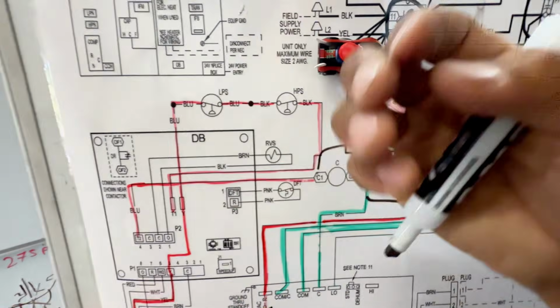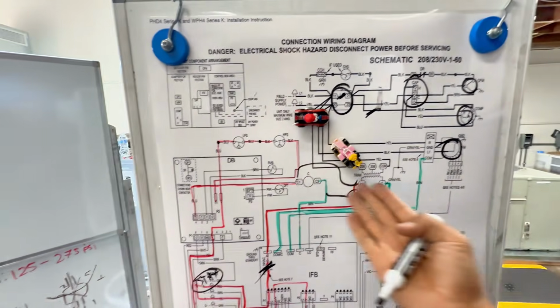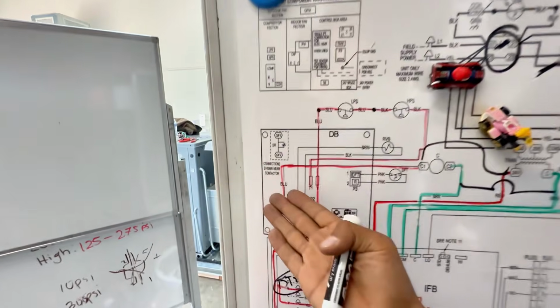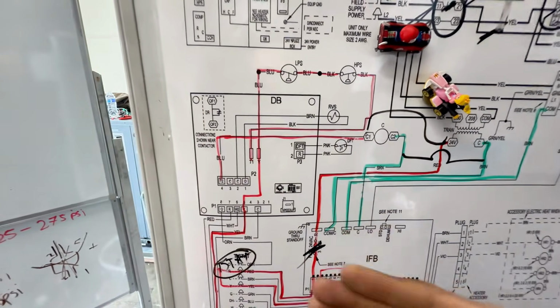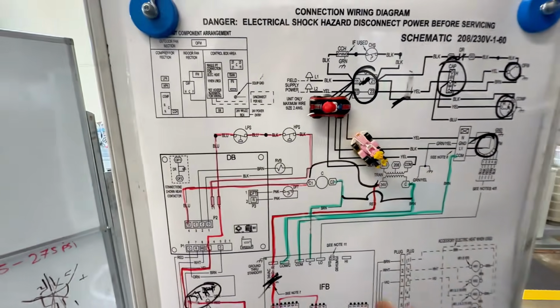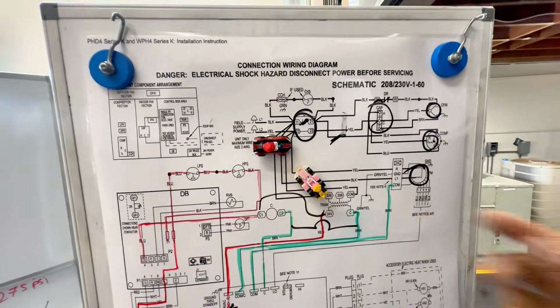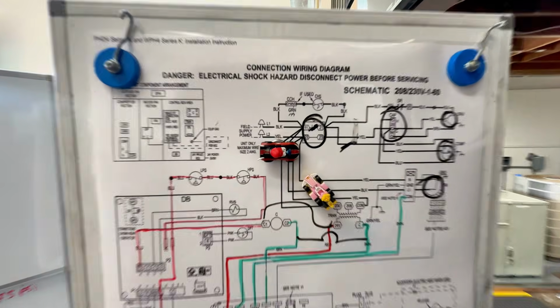That coil energizes, allowing high voltage to go through. So down here, we're just rerouting the 24 volts using temperature switches, in this case a thermostat, your pressure switches, yes, even the boards. It's just power in, power out. That's all we're doing when we're trying to understand wiring diagrams, whether they're ladder or pictorial.